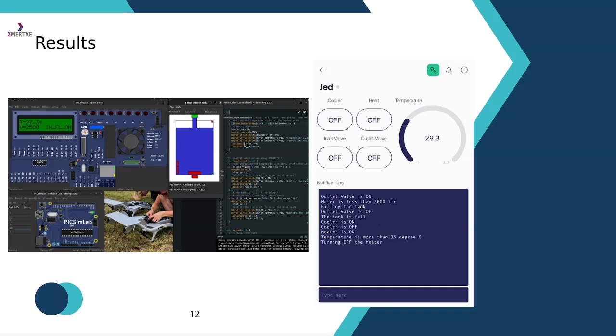When you turn on the heater, you see it moving here, you see it moving here, the T, where the T is temperature, then you see it over here too, that it is moving. But when it gets to 35 degrees, automatically it will shut down. The heater will go off, because we've written a code that prevents it from exceeding 35.